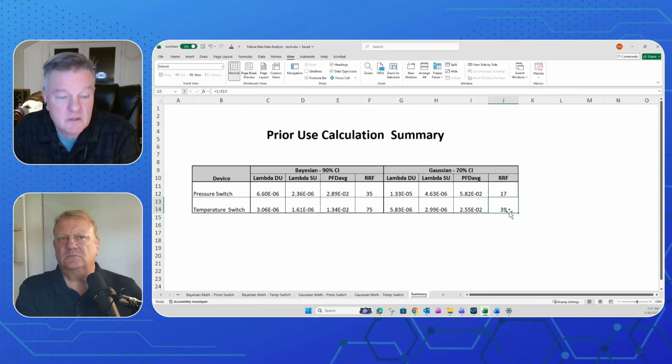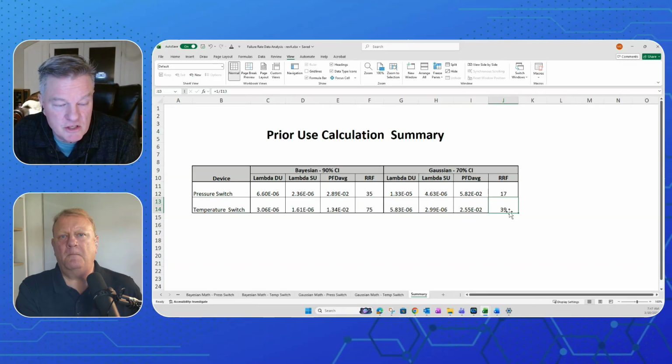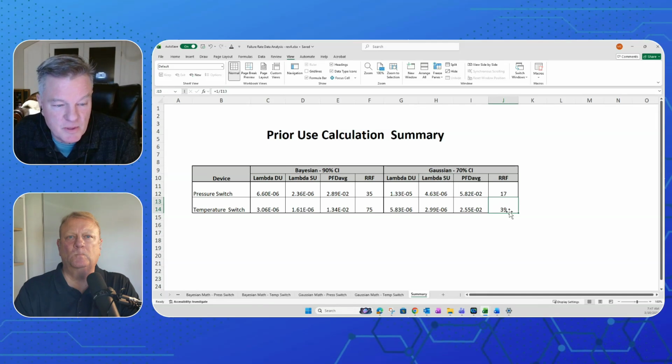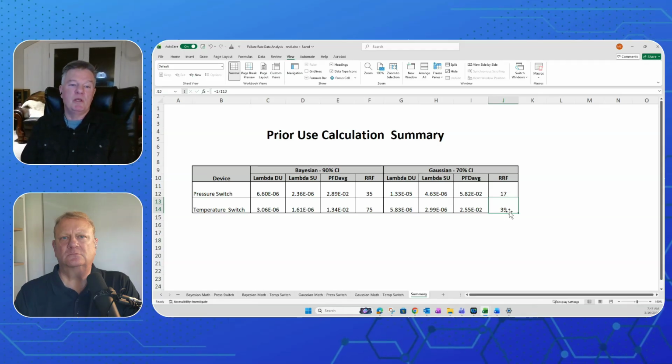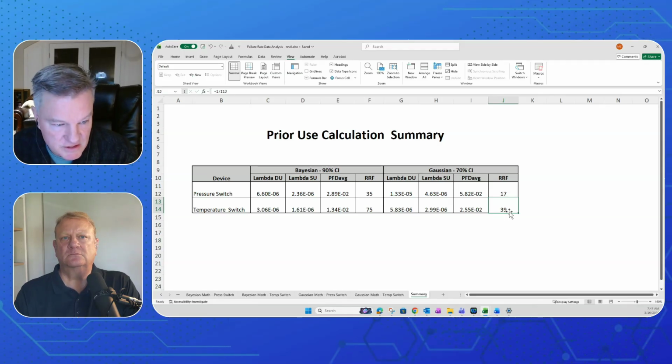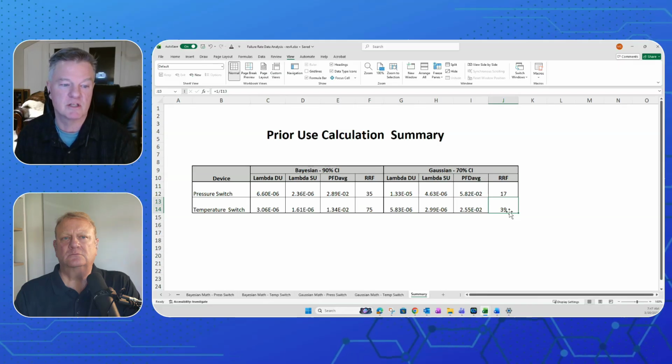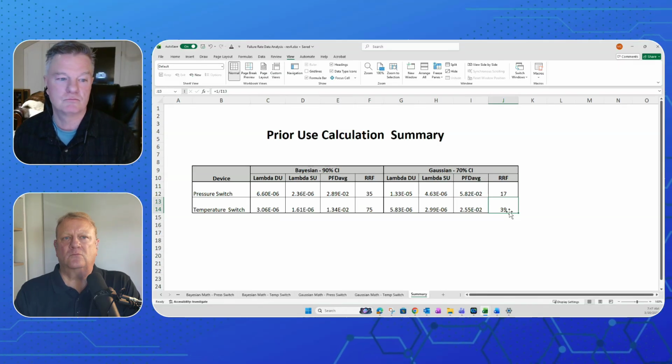Bottom line is I collected data. I analyzed the data. We did this in arrears. We had chicken scratch, so it wasn't like we changed the test plans. We classified the failures after the fact, ran the results, did a sample LOPA, and was able to show that we could, with redundancy and diversity of devices and actual failure rates, move testing out. And we'll come back to the money savings after the fact.